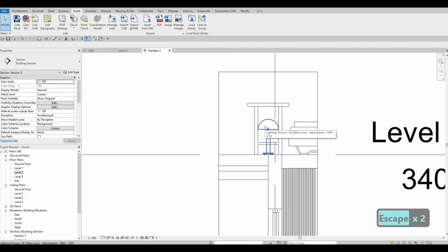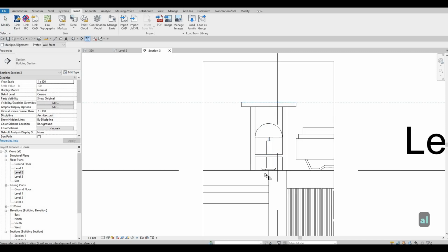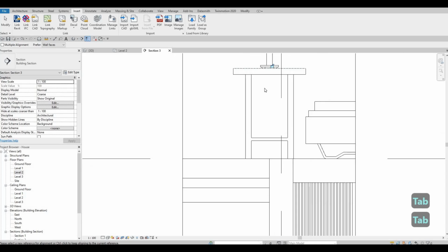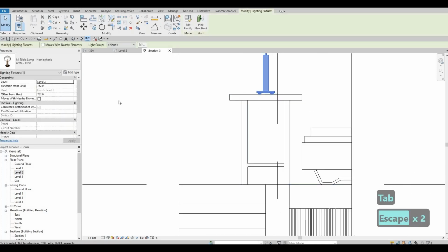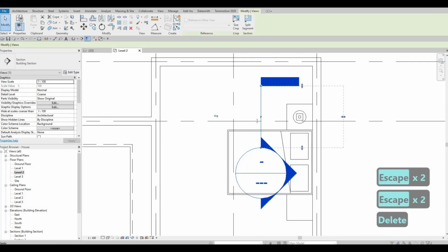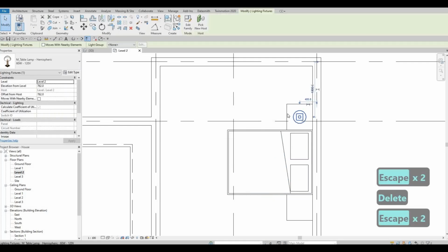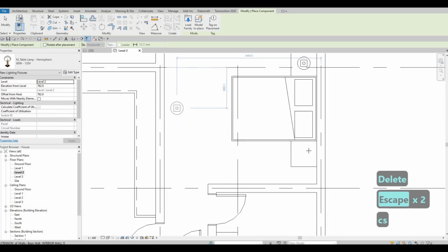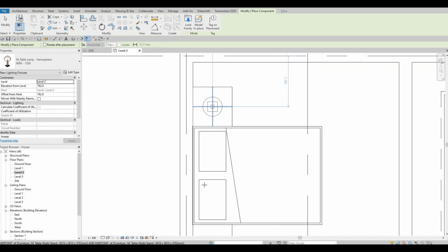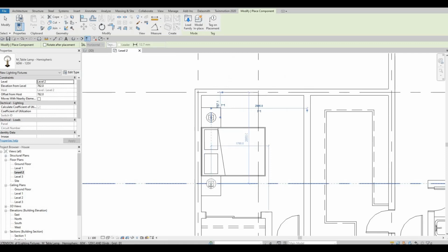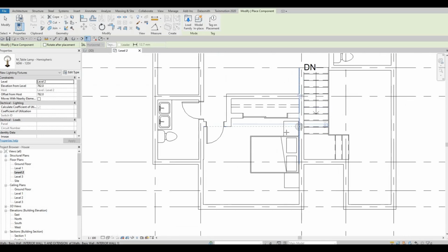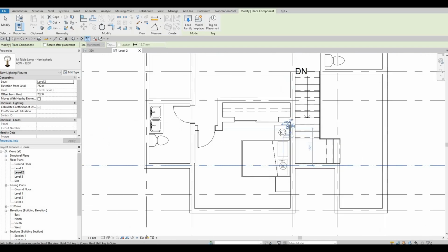So here what we could do is align it all the way to the top. There we go. So now it should be 762 from the top, but because we're just using CS, it will recognize the offset of the height. So we don't need to type in the 762 anymore because it registered whatever we added before.